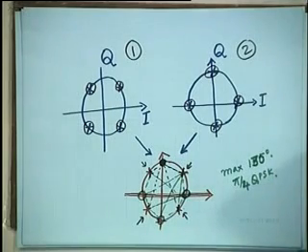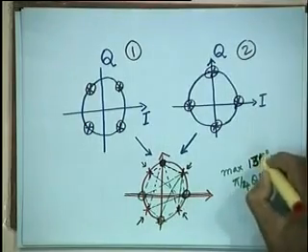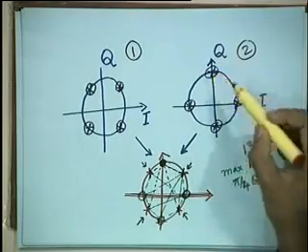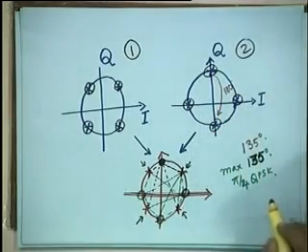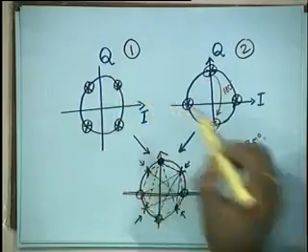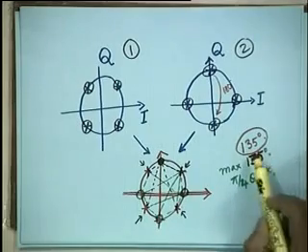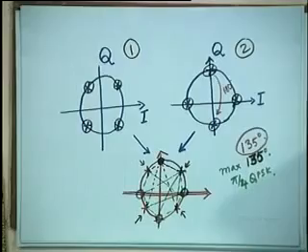So if you write it, in regular QPSK, it's possible to have 180 degree phase shifts. In your offset QPSK, it's only possible to have 90 degree maximum, and here you have a compromise between QPSK and OQPSK, giving you 135 degrees. So it's a very interesting way. The added advantage, of course, we have seen is it performs really well in the case of fading channels.